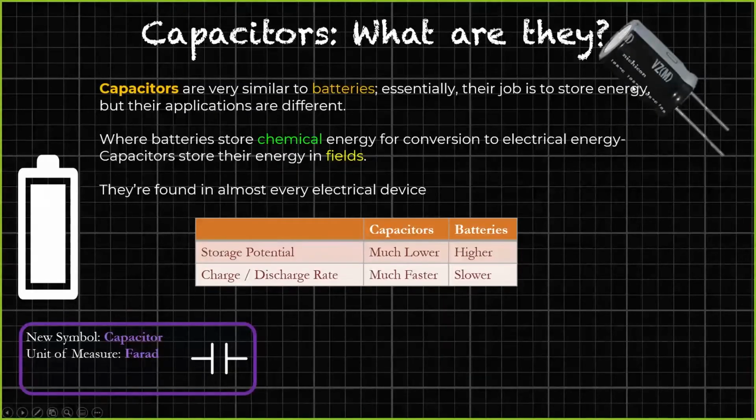I don't know why this isn't in there, but capacitors actually have a polarity. There is a positive side and a negative side. You will almost always see a stripe or a line on a capacitor, and that is the negative side. You want electrons entering that side, not positive charge carriers from the conventional energy transfer to go on that side. So just think the stripe side is negative.